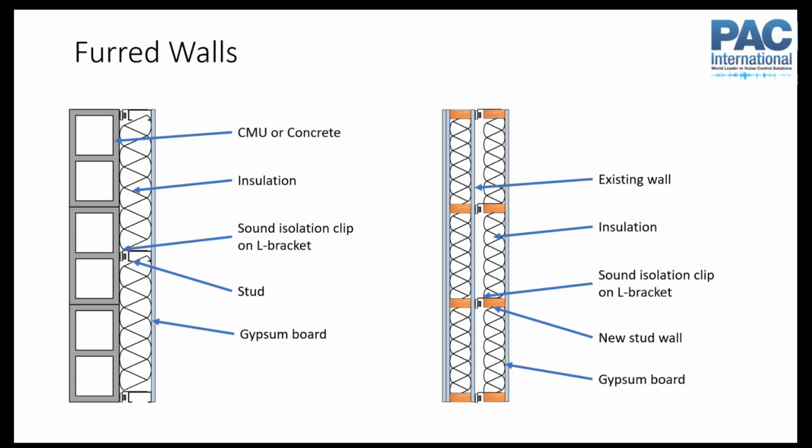And again, you want to use thinner studs, this kind of thing, but maybe it's a fairly tall wall, so you want to tie back to the structural wall, but you want to maintain acoustical performance. So you can use an isolated L bracket to give you that kind of structural tie back, but still maintain your acoustic isolation. So you've got better sound isolation between these two spaces.